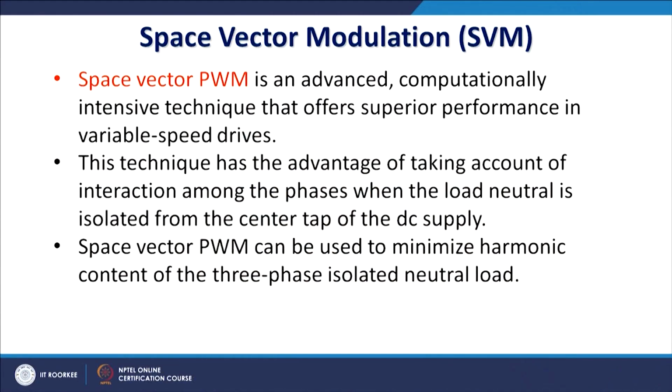Space vector is an advanced, computationally intensive technique that offers superior performance for variable speed drives. The same concept has already been used for different kinds of FACTS devices, STATCOM and all those things. So, whatever we do in V by F control and vector control, that concept is already used for FACTS devices. In FACTS devices also, this special kind of PWM technique, space vector modulation, is very important.